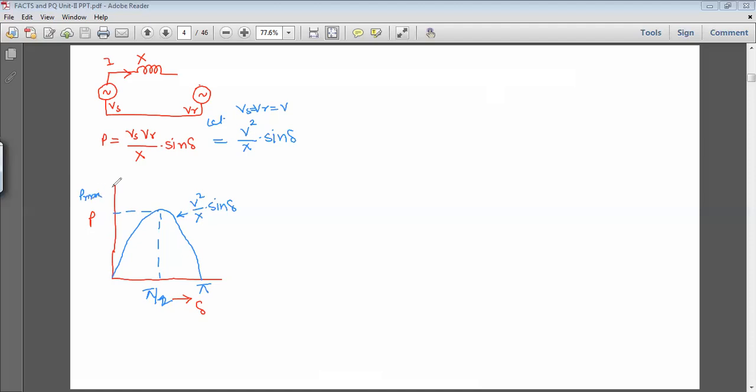Okay. Now let's consider the system which comprises the same thing, but we are going to connect one shunt compensator, and that compensator is an ideal compensator. It is connected in the center of the line, so the reactance gets divided into two parts: one is the sending end segment, and the second is the receiving end segment, and the rest of the transmission line is as it is.